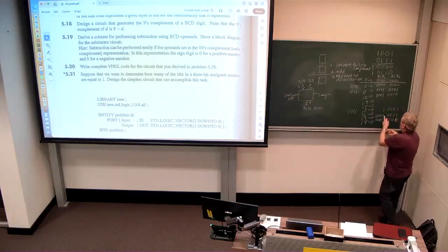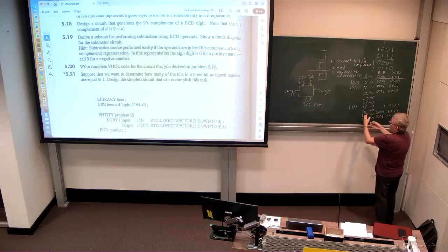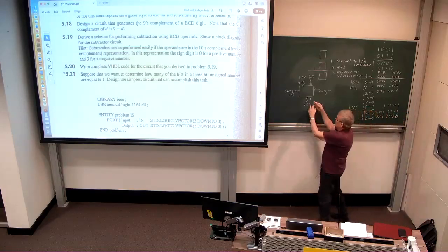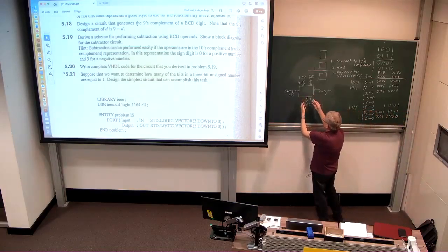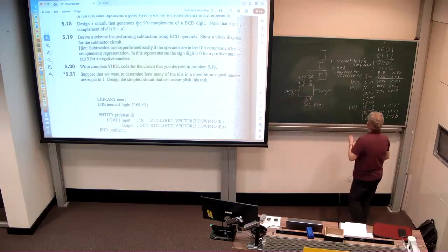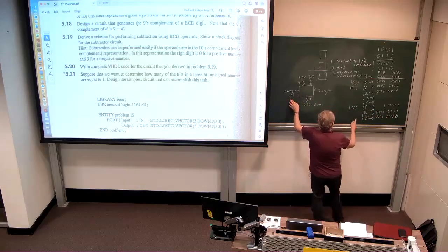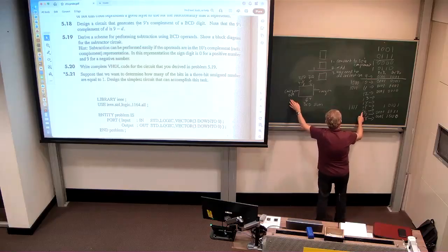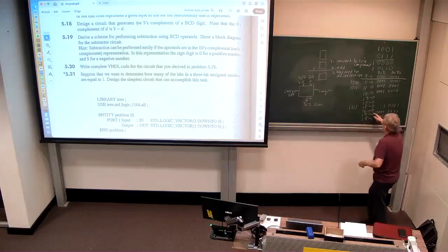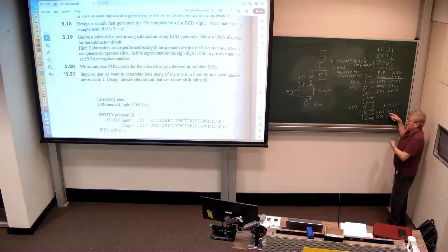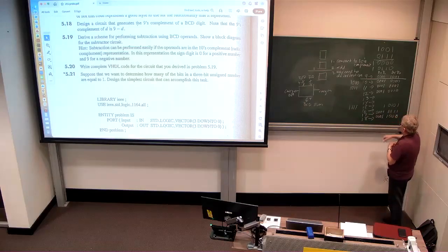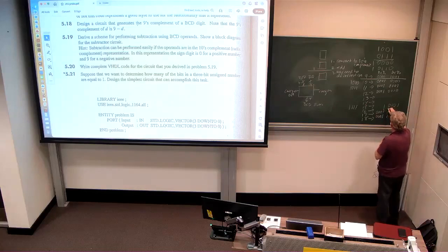But 16 isn't a BCD sum, well, it's not a sum that we can even represent. We know we've already got a carry out, so I guess once we get a carry out, which is indicated by the fact that we have at least 16, the 0000 that we have left over has to be converted to a 6, right?